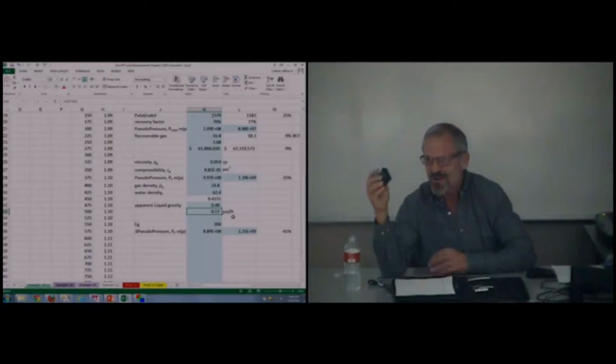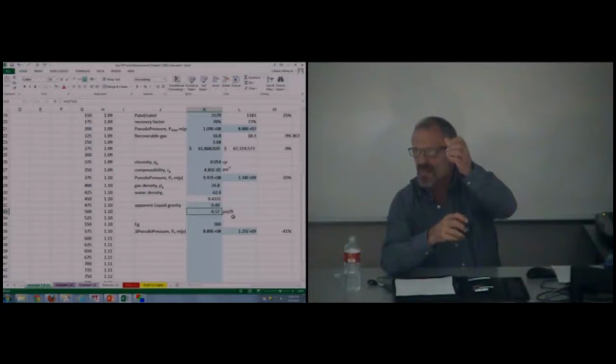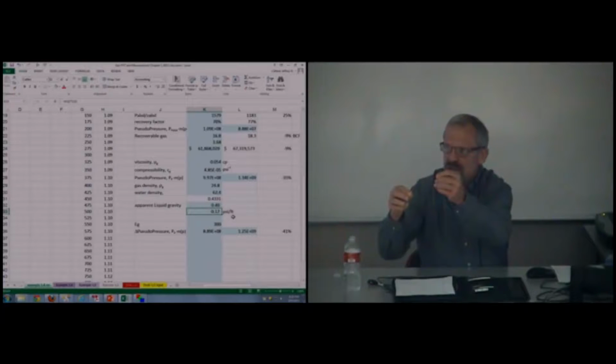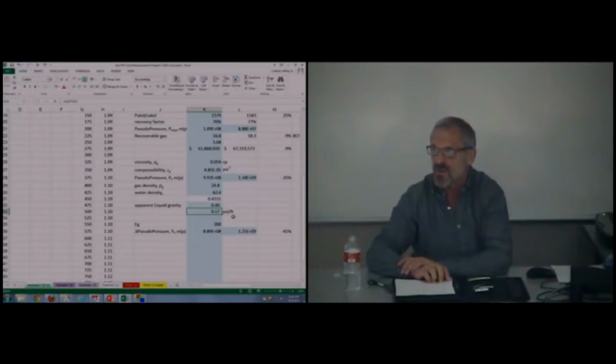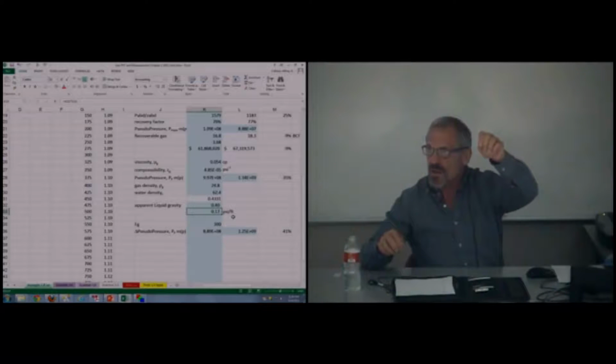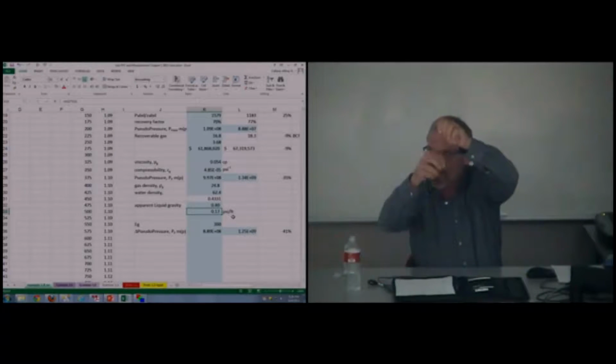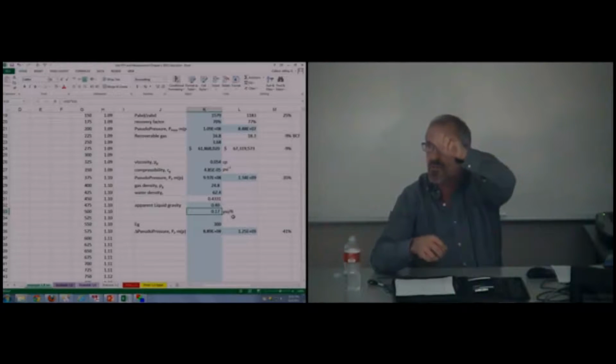But there's another meter that we lower into the well that measures the pressure. So if I measure the pressure at two different places, I get a pressure gradient in PSI per foot, right? Let's say I measured the pressure just 1 foot away. Then the difference in those two pressures is the pressure gradient in PSI per foot. If I measured the pressure 10 feet away, remember, it's always getting higher pressure, then I'd have two pressures, and I'd have to divide the pressure difference by 10 to get the pressure gradient in the units of PSI per foot.